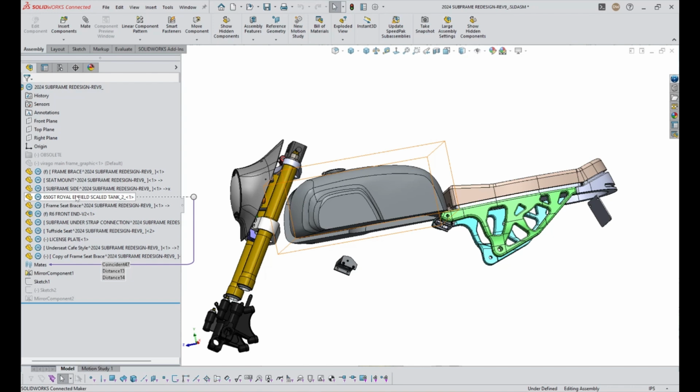Now, reasons why you might do this is, like I said, prototyping. But have you ever opened up some files that you haven't worked on in a while, like assemblies, and a lot of things break because files that they were referencing also broke or were modified? When those individual parts get modified, then the assembly is just a product of all of those parts, essentially. So you lose a lot of those references. But when you make the parts virtual or subassemblies virtual, they are saved within that assembly. So you are preserving that assembly as it is. It cannot be changed by any other external references. So it's a great way to kind of seal everything together.